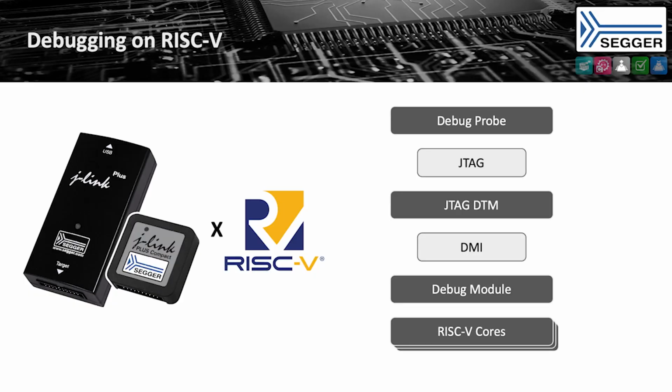So let's start with a bit of background of how debugging is enabled on RISC-V. We're talking about the specification for RISC-V external debug support, the de facto standard for native debugging. And we're debugging with a regular debug probe through the standard JTAG debug transport module. Or to be more precise, the probe goes through the JTAG TAP and the DTM to use the debug module interface to talk to the debug module. And then the debug module is connected to the RISC-V cores, or harts in a multi-core system.